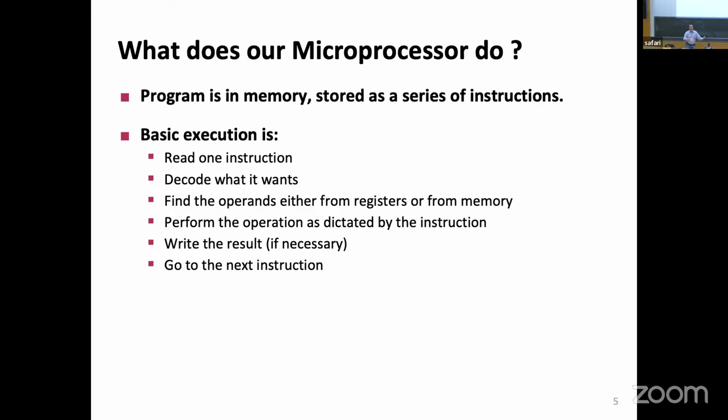I have 32 registers to choose from. This means that I need 5 bits to tell them apart. And for every address, I have a corresponding output of 32 bits. So this is the read 1, this is the read 2, sorry. Now, part of this instruction contains which register I am choosing. I can pack them because there are 5 bits here, 5 bits here. A few of the other bits tell us other things. So I can manage this.